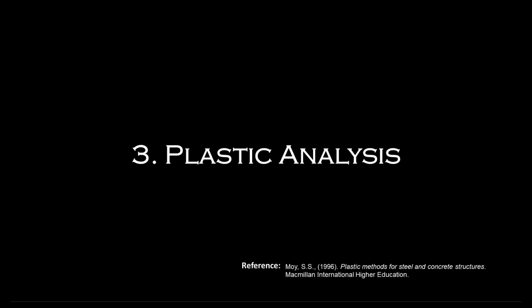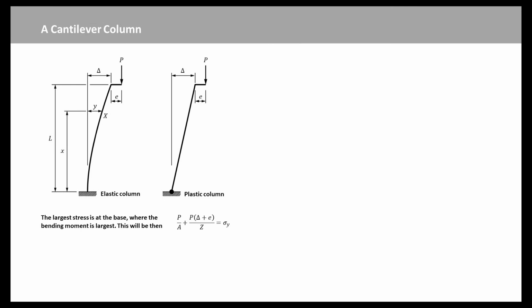Now we will introduce the plastic analysis. In the column, there is a combination of axial and bending stresses. The largest stress is at the base, where the bending moment is largest. When this stress reaches the yield stress, the elastic analysis will cease to be correct.